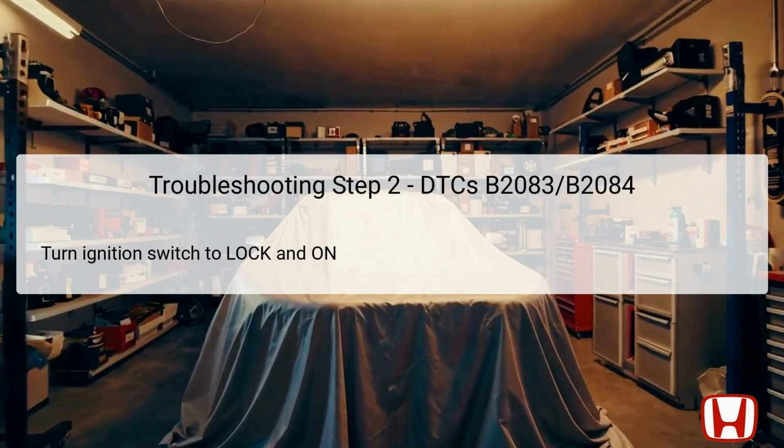The next step requires turning the ignition switch to the lock 0 position and then back to the on 2 position. This procedure helps to ensure that all electrical systems reset correctly. The process allows the vehicle's onboard computer to initialize the components involved with the power sliding door.